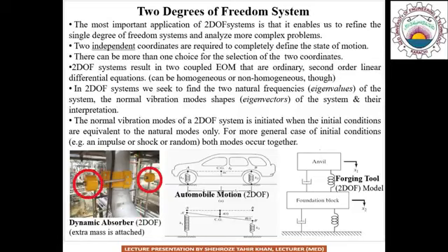As a result, the amplitude of vibrations of the primary mass, that is the process pipeline in this case, is reduced. So if the pipe vibrates in the coordinate direction x, the secondary mass will also vibrate in the same direction with different amplitude, and thus it is a 2 degree of freedom system.